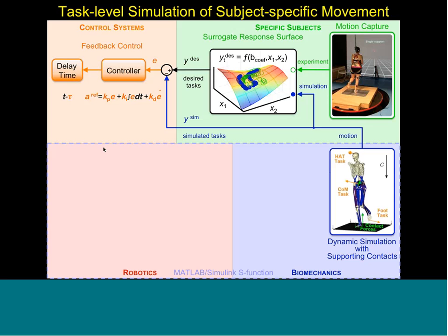So to answer this question, you can define how long you want your simulation to be. There's a place where you can assign, for example, a 10-second simulation or a 5-second simulation. The forward dynamic simulation itself is relatively fast. It's faster than running forward dynamics in OpenSim, and the reason for that is they're using some kind of MATLAB integrators to do the integration inside.